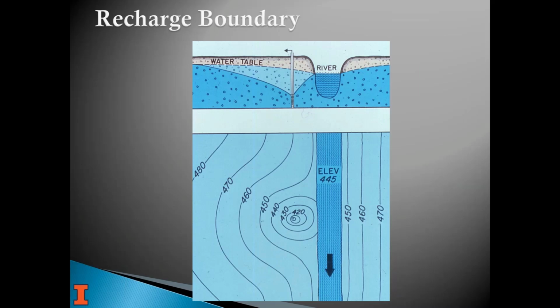I mean, you're not stressing it in particular. It depends on if you have a 5 gallon per minute pump or 15. If you have livestock, you might have a 20 or a 30. But what really matters is how quick water can replace the water you're taking out of the well as it moves toward it, and what volume of water is available around the well. The porosity dictates how much water there actually is around there, and that indicates what you're going to see when you pump your well.